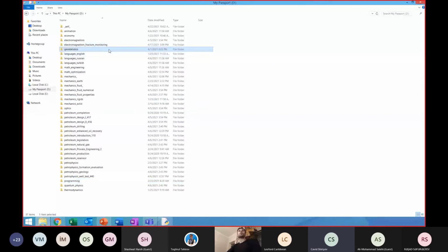And then we are incorporating our constitutive equation, which is the Darcy equation, for Newtonian fluids. And then we are implementing the equation of state. For example, for the oil, we can assume the slightly compressible model. And if we add all those equations together, we're going to get the final form of the diffusivity equation.